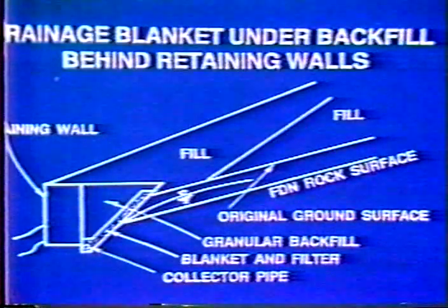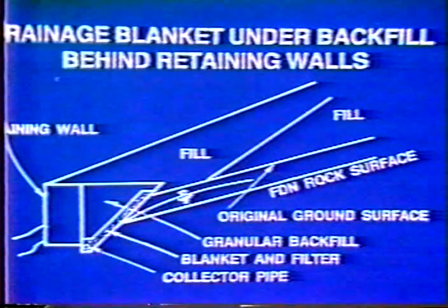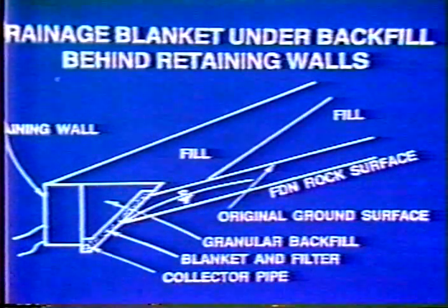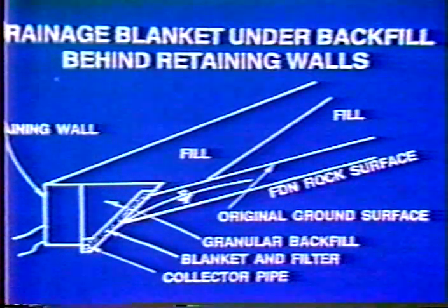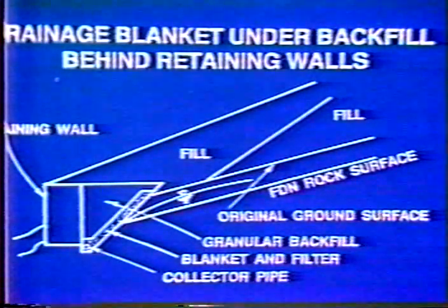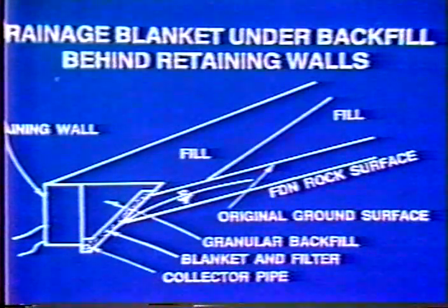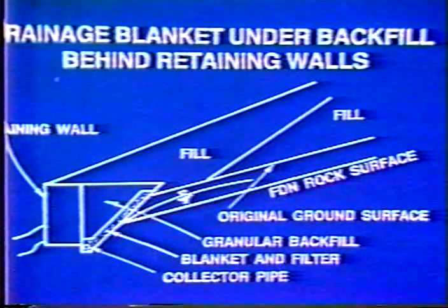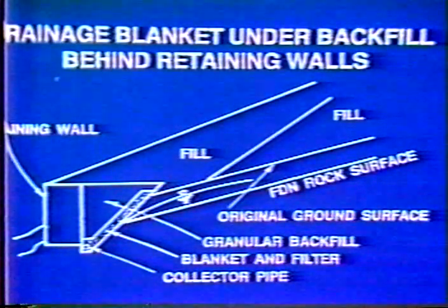Another situation where it's good to use a drainage blanket is under the backfill or behind retaining walls. Again, we wrap the stone with a geotextile. Again, we're trying to keep the water table back out of the backfill or behind the retaining wall.